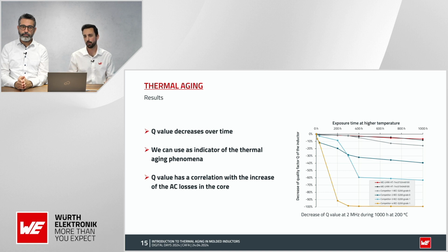For sure, all these parts are qualified grade zero in the AEC-Q, and some of you might ask, why is this process not identified during the qualification? Because in the qualification, it is checked which electrical parameters appear in the datasheet. If the Q value doesn't appear in the datasheet, it will be impossible to identify it.